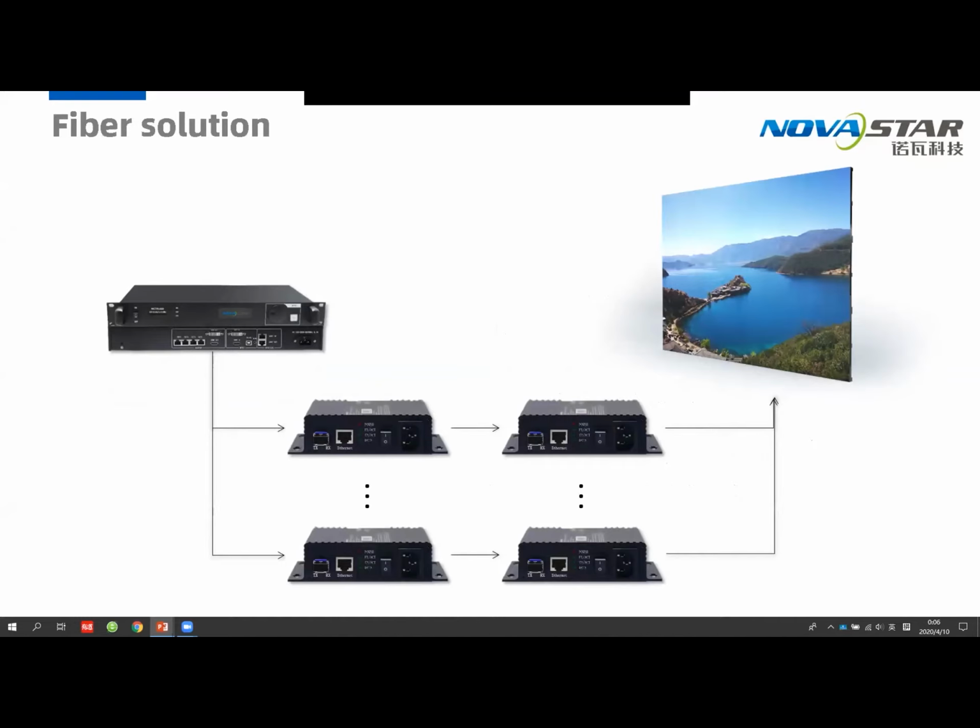Normally our video wall will be 2K by 1K resolution or more. Here we take a 2K screen as an example, and we need full output. Just now we mentioned each port needs 2 pieces of CVT. So in total how many do we need?